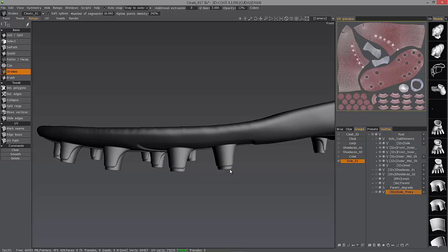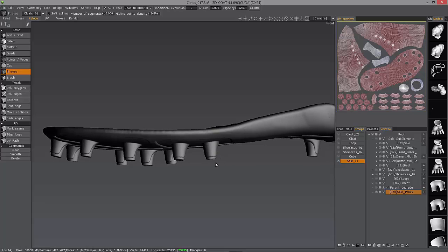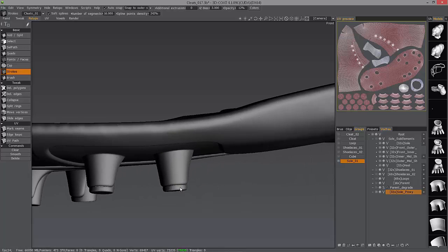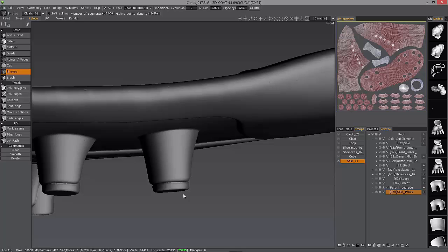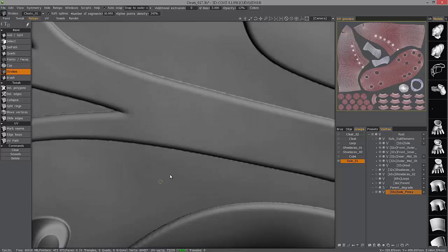To help prevent any perspective distortion, I like to go to orthographic view when I'm using this tool. Start outside the object on one end, click and drag to the other end and outside the object as well. Because if you start inside the object, 3D Coat is going to assume you want to make just a single stroke here. But if you start outside and end outside, it will try to create a loop.